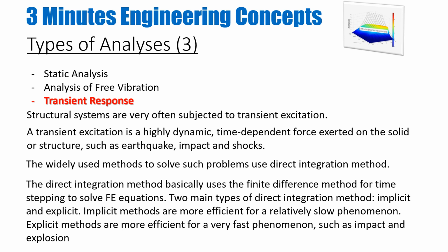So you use different types of direct integration methods. One of the basic methods which is widely used in FE software is the finite difference method for time stepping while solving FE equations. And there are two different types of direct integration methods. One is called the implicit method and the other one is called the explicit method.